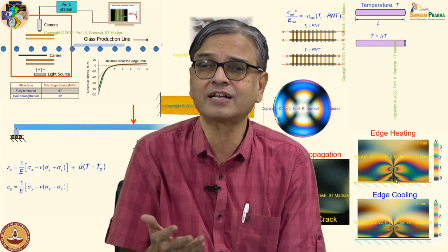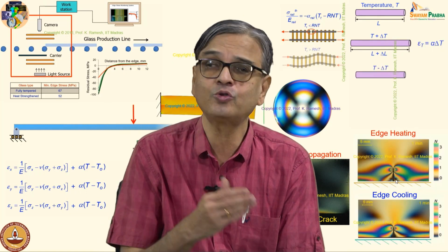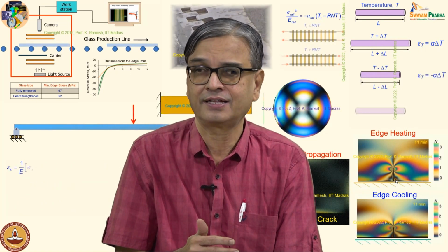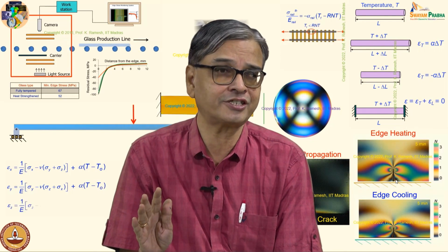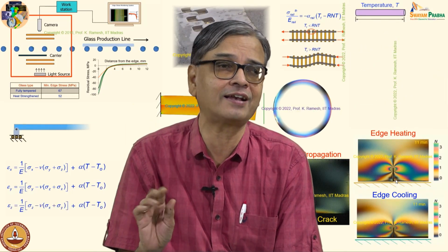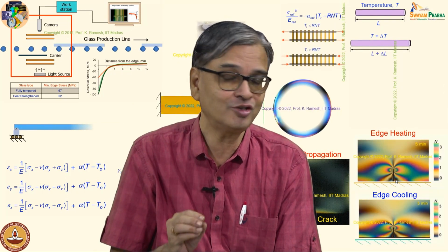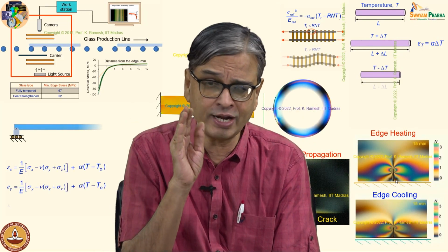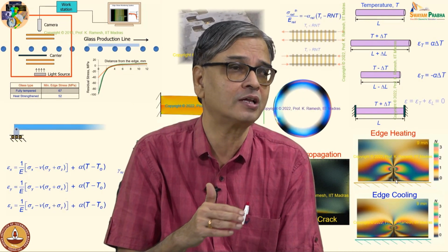But if you have constraints, you also have the stress strain temperature relation for you to evaluate the thermal stresses as well as thermal strain. And the recommendation here is, when you write the stress strain temperature relation, do not simply say strain as alpha delta T. Alpha delta T may be a special situation when there is no constraint. So, these are all the ways you can make a mistake. So, write the complete expression including the stress terms plus the temperature terms and knock off those terms which are 0. Thank you.